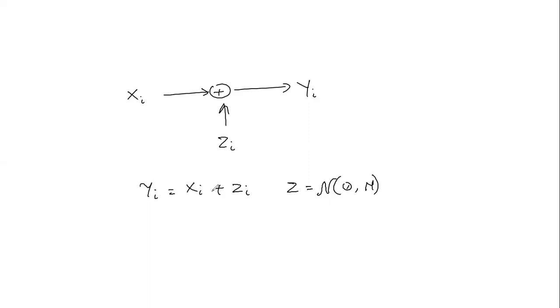So hence, we have to assume an average power constraint, okay? For any code word, say S1, S2, all the way to Sn, transmitted over the channel, we are going to require 1 over n, since we have n symbols, 1 over n is going to give us the average of the total sum of the power. So that's the sum of S sub I squared, which should be less than or equal to P, okay?